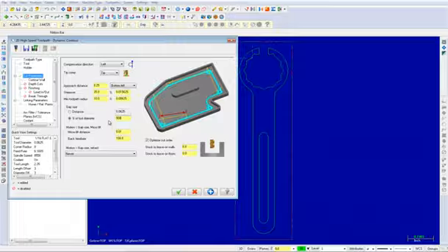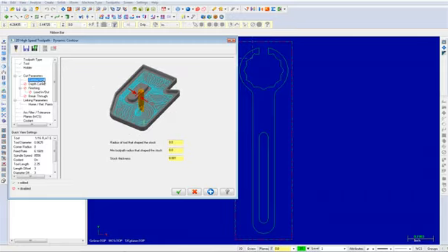Min toolpath radius sets the minimum toolpath radius used in combination with the microlift distance and back feed rate parameters to calculate 3D arc moves between cut passes. Once the parameters have been adjusted, select Contour Wall. Make the following changes. Ensure that the radius of tool that shaped the stock is a value of 0.125.